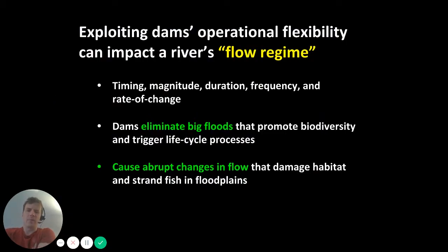Back to this issue of flow regime. One of the issues with hydroelectric dams, in particular the conventional dams that are strategically controlling the storage and release of water downstream in order to maximize the value of hydropower production or provide flexibility to the grid, is that operating in this way can significantly impact a river's flow regime. So again, the timing, magnitude, duration, frequency, and rate of change of river flows.